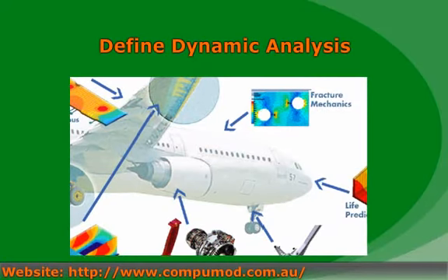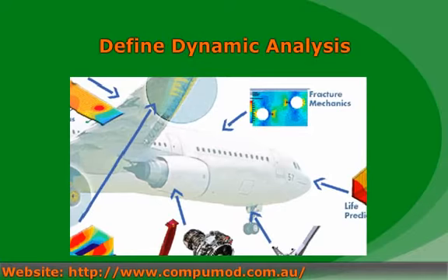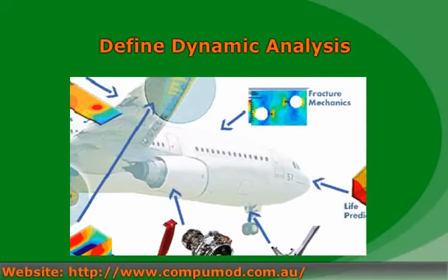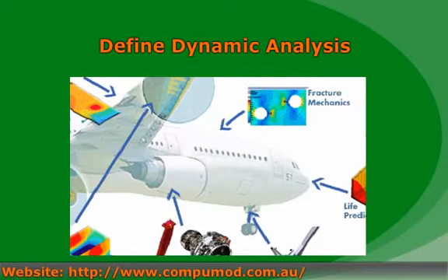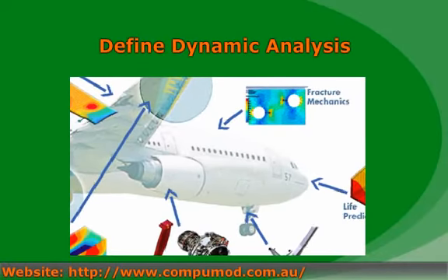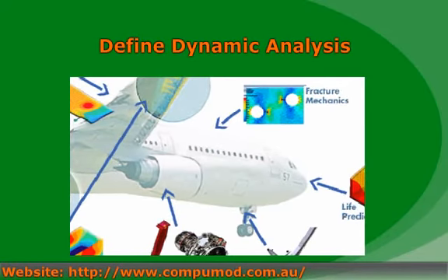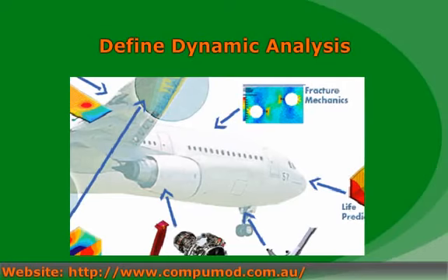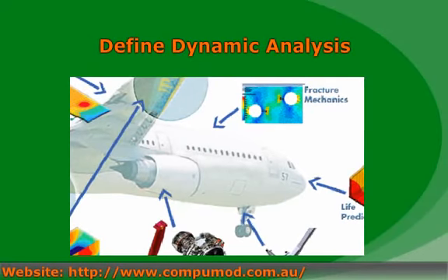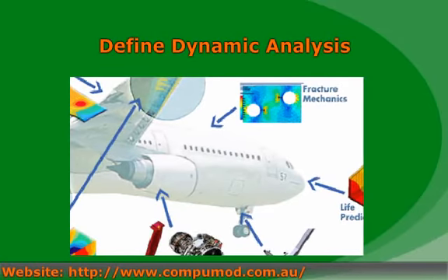Define dynamic analysis. Dynamic analysis of three-dimensional structural systems is a direct extension of static analysis. The elastic stiffness matrices are the same for both dynamic and static analysis. It is only necessary to lump the mass of the structure at the joints. The addition of inertia forces and energy dissipation forces will satisfy dynamic equilibrium. The dynamic solution for steady-state harmonic loading, without damping, involves the same numerical effort as a static solution.